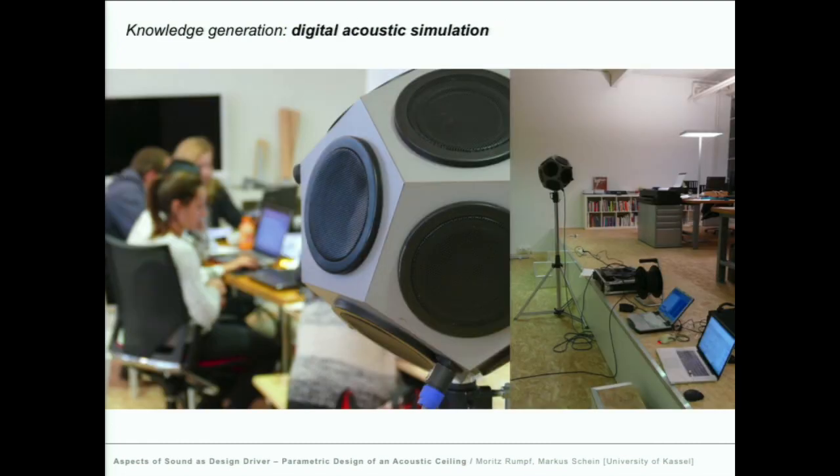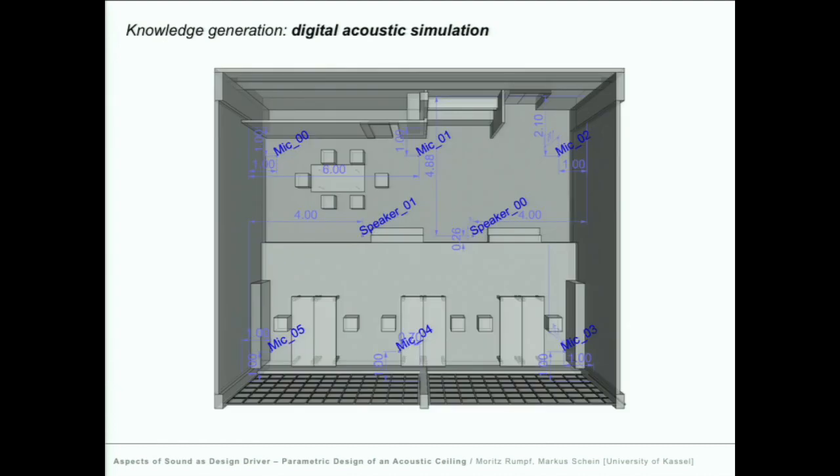We also tested the use of digital acoustic simulations for their benefit for geometry formulation, for evaluation of variations, as well as predicting and validating a desired performance. In order to assess the initial situation, a standardized acoustic measurement was carried out, which you see in the image. The setup for the digital simulation is analogous to the actually conducted acoustic measurement, whereby 6 receiver positions are measured with 2 speaker positions, and the 12 measurements are interpolated respectively.